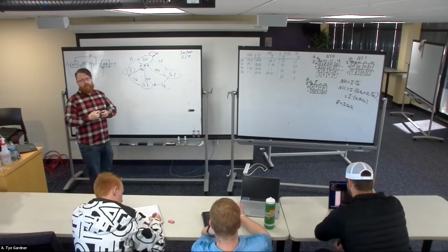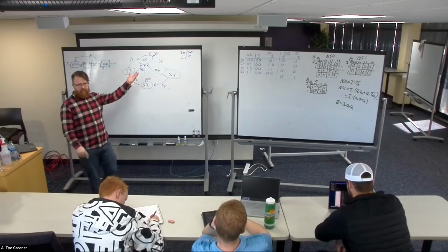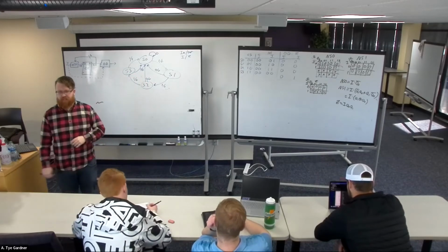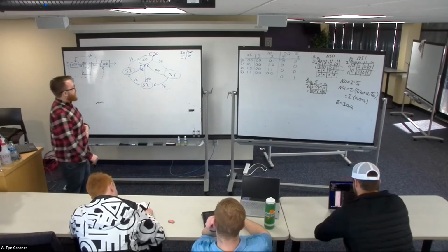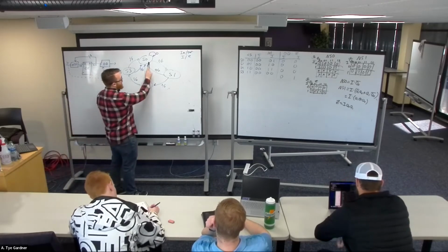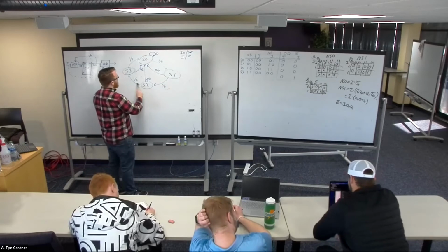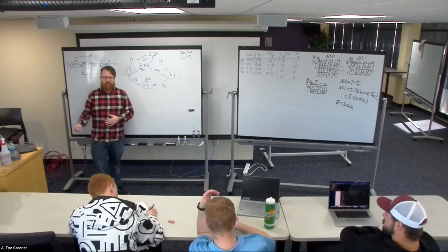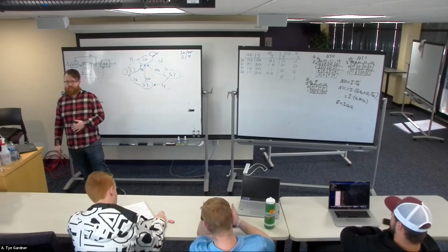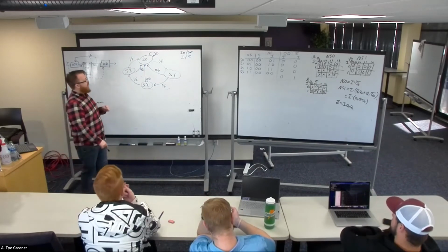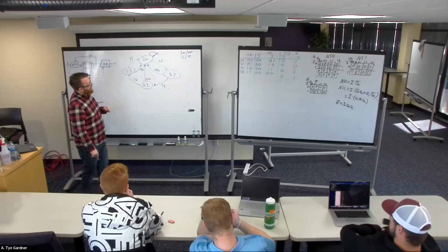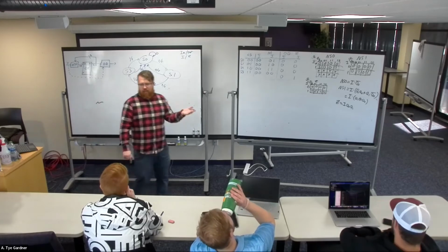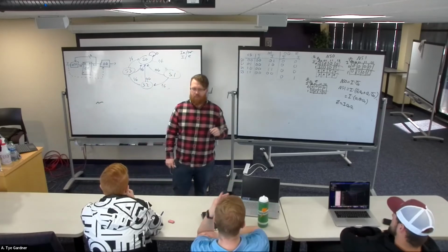We can then go back and look at this and kind of evaluate what this is. I literally just pulled a random one off the internet, had about the right number of states and transitions as I wanted. But basically it's saying that if it sees the sequence 1, 1, 1, 1, the output is 1. It's looking for the sequence 1, 1, 1, 1. It does not, however, detect, well, maybe it does. Well, anyways, we'll get into that later. But that's all it's looking for, is looking for 4 ones in a row.